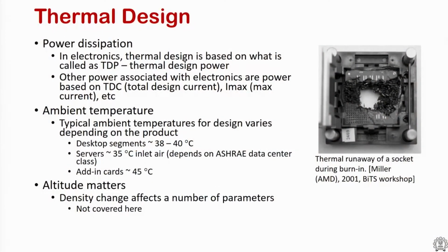With that definition, we move to an example on the right hand side that shows a processor that had a thermal runaway situation when sufficient cooling was not provided. You can see that the device actually burnt out. There is a big hole in the socket itself during what is called burn-in. Burn-in is a testing phase of a processor, and the thermal runaway situation that I had discussed in the previous slide is the reason for the complete burnout of the processor.